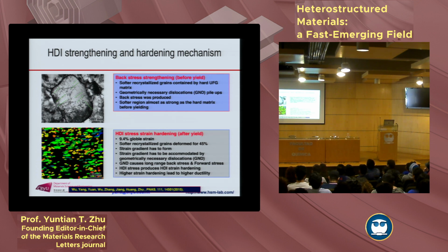However, it is surrounded by the harder matrix. The matrix is still elastic. It really cannot go across it, which means even when it cannot go across, whatever plastic deformation happens here does not register when you do the mechanical testing. You do not see the plastic deformation in mechanical testing, or you do not see enough to register. And so this started way before the yielding point.